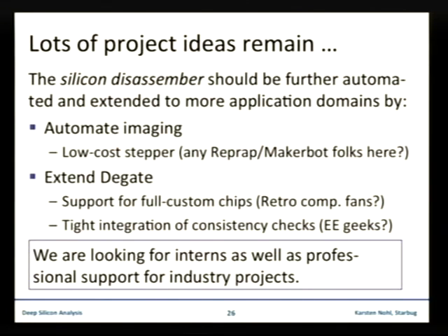So if anybody has an idea of how to create one cheaply, like the RepRap, but maybe an order of magnitude finer. I have a quite simple idea. Take an old hard drive, then you have a linear drive, and if you apply DC to the coil, it moves in one or the other direction, okay. And then you should get some position, and so you can make a mirror and maybe some CCD scanner line, and then you know where it's moving.